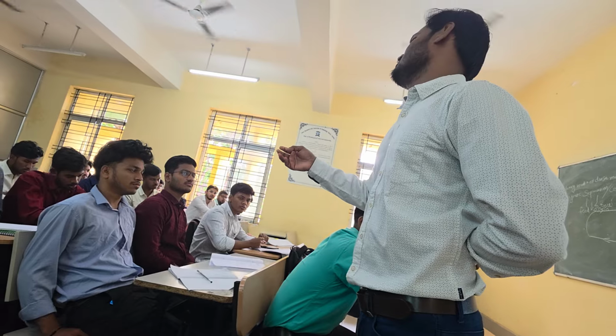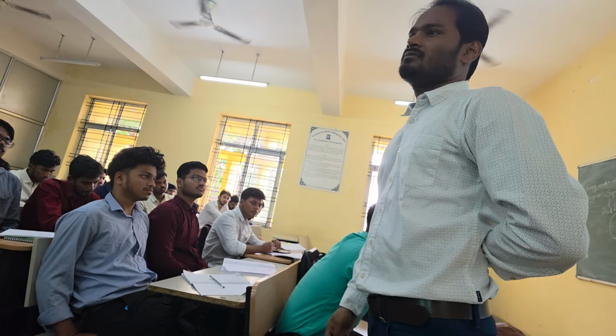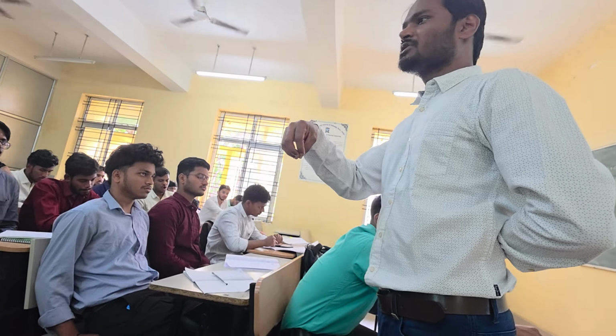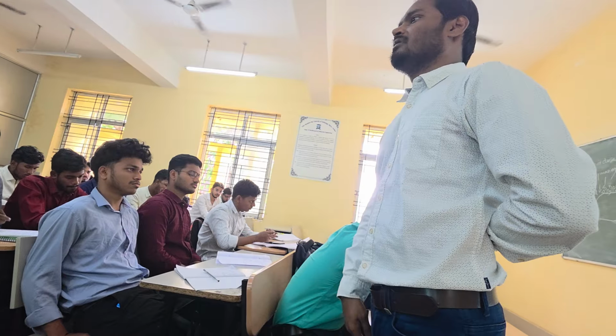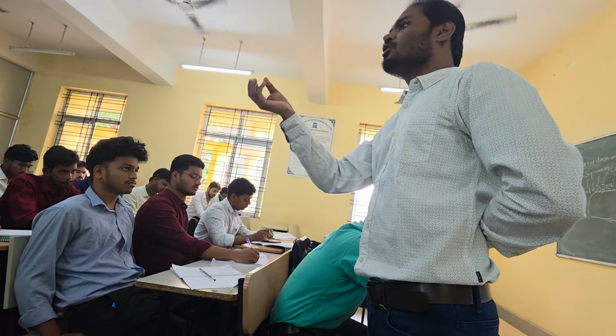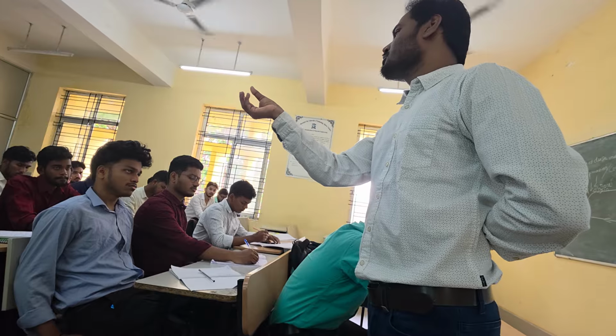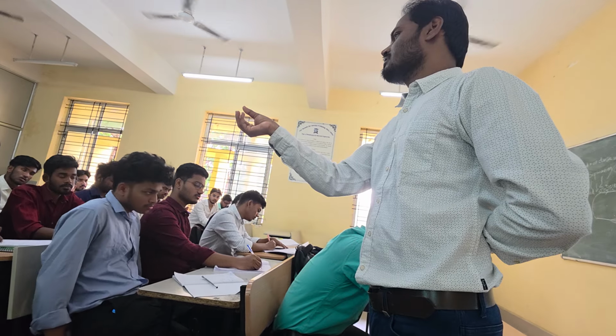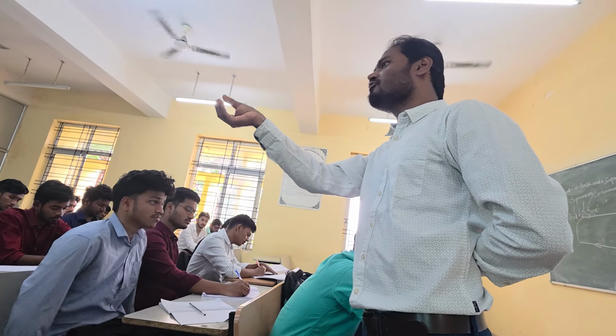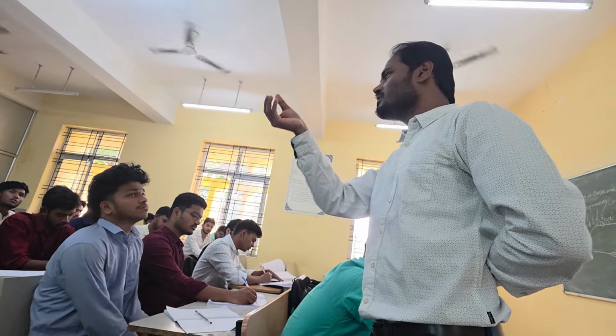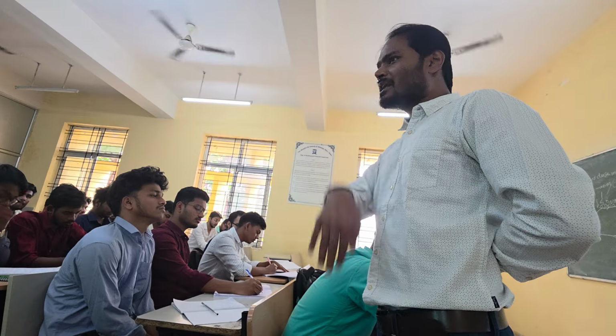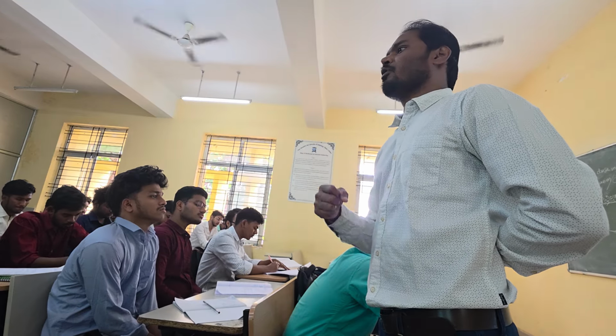Maybe around 10 to 15%. You need to add moisture, only 10 to 15%. If you increase the amount of moisture, the ball will be soft. It will be plastic, it can be deformed easily, and it can flow. But if you add very little water, the binding will not be proper.